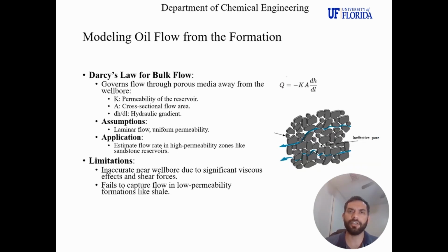Darcy's law is the go-to model for flow in porous media. It relates the volumetric flow rates to the reservoir's permeability, the cross-sectional area of the flow, and the pressure gradient. We have a simple equation here. We use Darcy's law to estimate the flow rates in high permeability reservoirs like sandstone. However, it assumes laminar flow and does not capture complex effects near the wellbore or in low permeability zones. To address these limitations, we turn to the Brinkman equation.